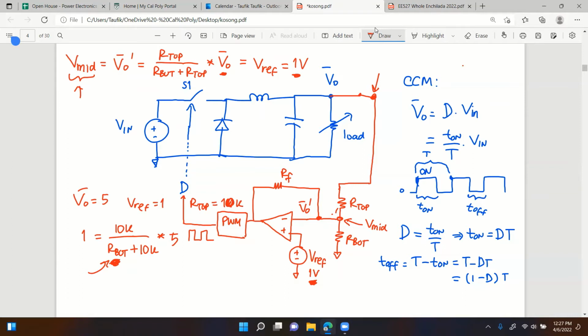The reason being the change could be sudden. It could be a step change, and that could cause problems. If you just have a gain, it can cause overshoot, a percent overshoot that's going to be too high, or it could cause long oscillations.